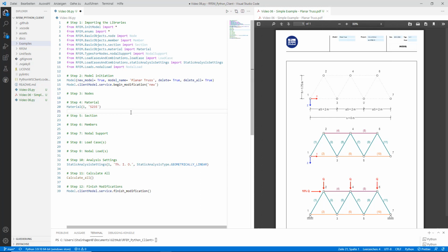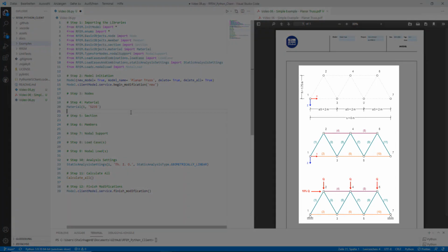The first bullet point, working with multiple members, is crucial because insufficient attention to numbering is a source for most bugs. When numbering isn't sequential, or when a number repeats itself, analysis errors and/or incorrect structure definitions occur. We want to, in this example, define a simple truss as shown on the right.